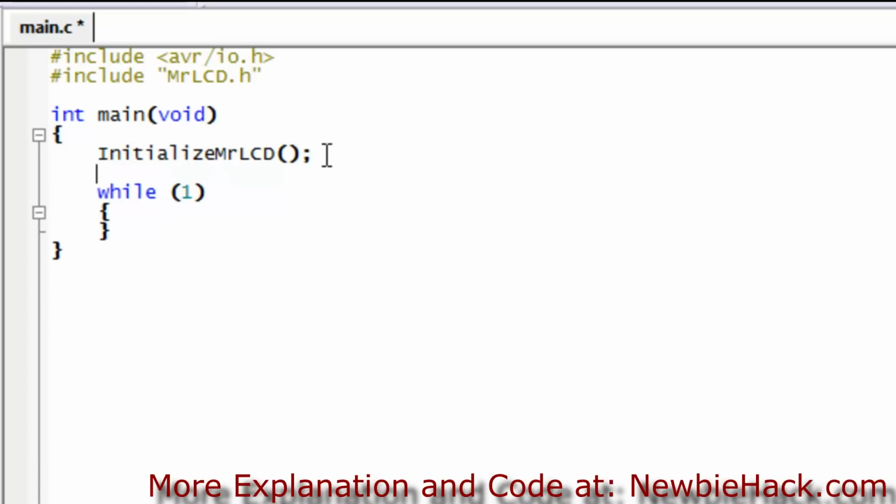Next, we want to configure the analog to digital converter. And this will generally happen not in the endless loop. We have two options when it comes to the function of the analog to digital converter: having the ADC finalize conversions through interrupts, or just determining if a flag is set or not, and then reading the results.